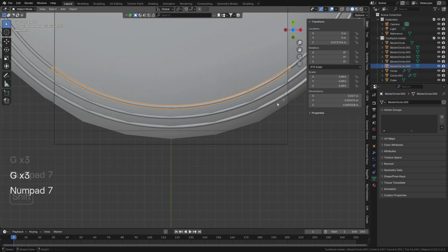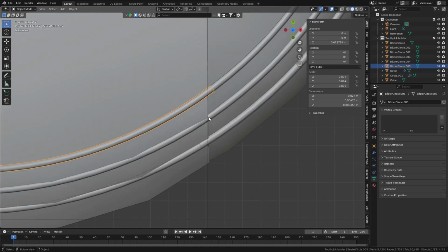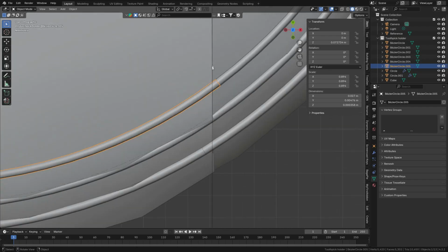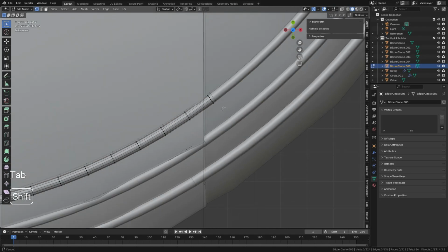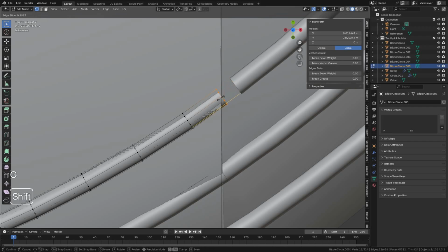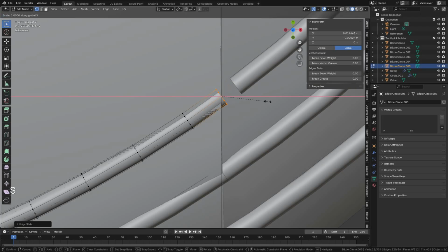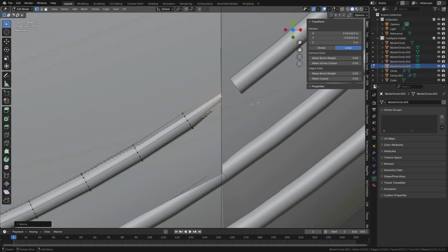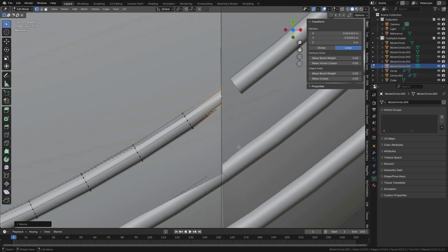Now before we go on, what you want to do is edit them so they are right along this edge here, where the toothpick cap is, or where the boolean is giving us that line. So select, for example, this first curve, go to edit mode, select this, double tap G on the keyboard, then slide it in along its normal axis. You can press S, then X, 0, enter, then scale it up. So it should just be about there.